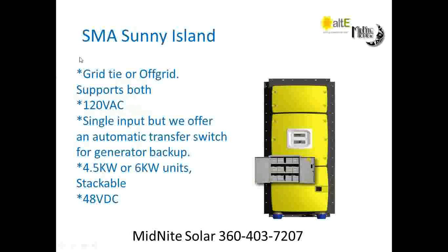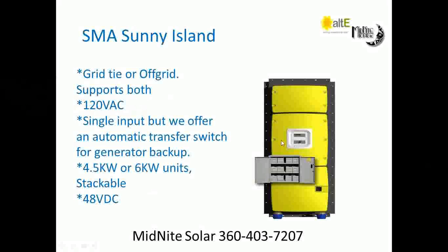And again, that autoformer and that transfer switch take care of the current flow problem, because the Sunny Island, being 120 only, is limited to 56 amps at 120 volts. But where we move the grid tie inverter between utility and backup, that no longer becomes a problem.